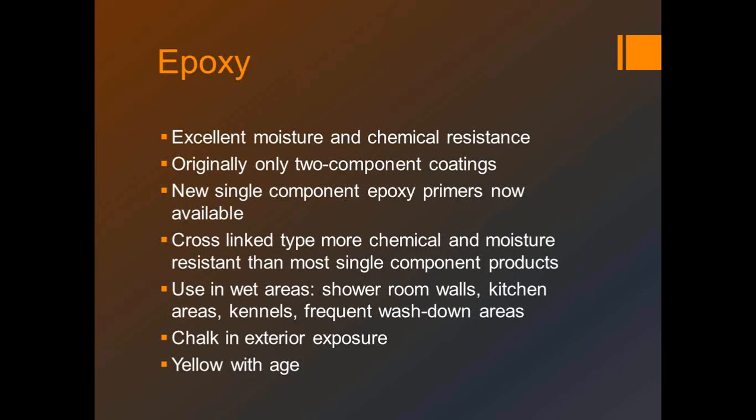And yes, to a large extent, yes. There's a lot of epoxy flooring systems out there. Epoxies and floors are very dependent upon several things. Some of the questions that you need to ask when it comes to epoxy on floors, first and foremost, is there a vapor barrier underneath the slab? And if we get a yes answer to that, then we need to do a moisture check, either do calcium chloride checks, or even something as simple as taping down a 2 foot by 2 foot piece of plastic